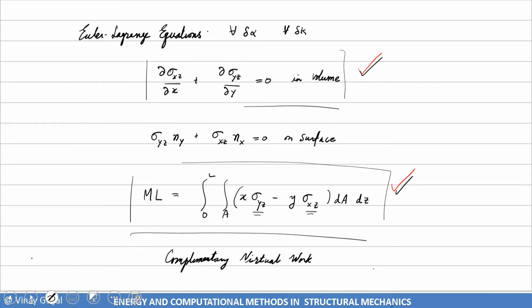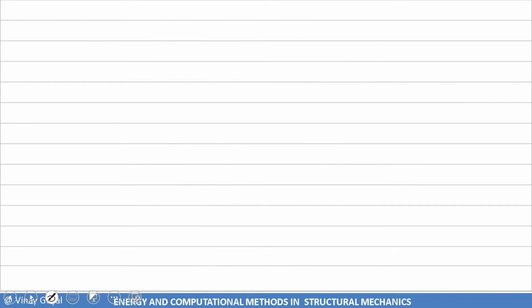And really what I want to do is calculate torsional constants for various problems, and I want to be able to determine how much warping I get. In addition to that, I want to determine what is the rate of twist. All that will be very useful, but I'm not able to get there particularly with this approach. And so for that reason, today I'll be introducing a different approach, and that approach is using the total complementary energy functional.